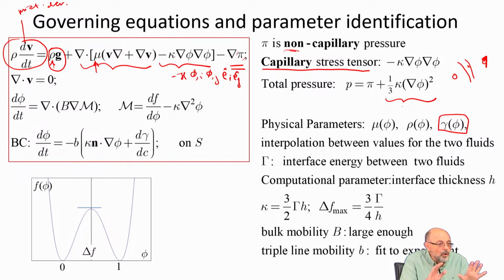My two fluids flow following the same equations, even though their viscosities and mass densities are vastly different. Together with this conservation of linear momentum equation, there goes incompressibility equation. My liquid is certainly nearly incompressible. Gas is compressible, but I will not be building up any pressures here in the gas. So gas is compressible, but we don't care. So we call everything incompressible.